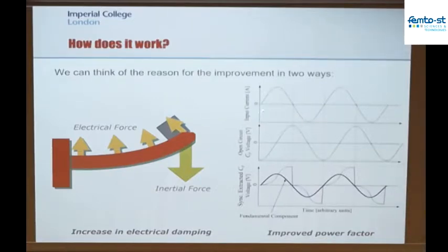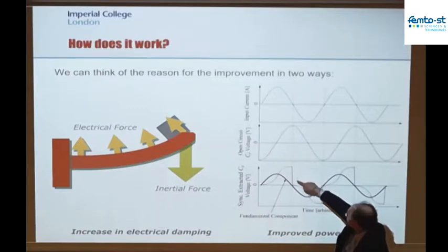If you look at the input current produced from the current source in the piezoelectric material, of course that gets integrated onto the capacitor of the device, and that is therefore the voltage that you would see on the capacitance of the device if you didn't change anything, if you just allow the piezo to wiggle up and down. If you put some of this charge in here, and here's an example where we just short the voltage to 0 rather than actually flipping it.